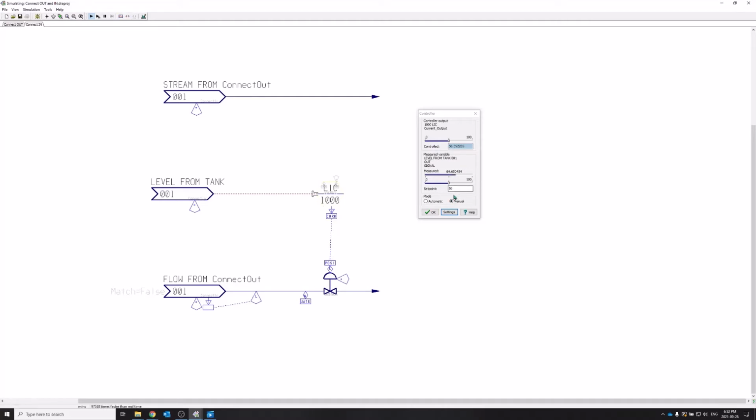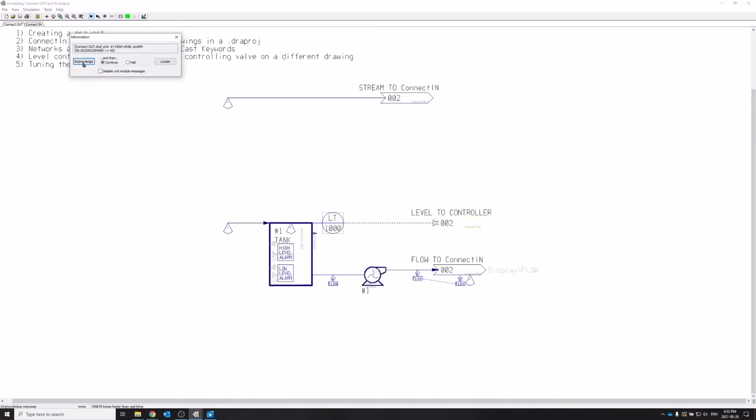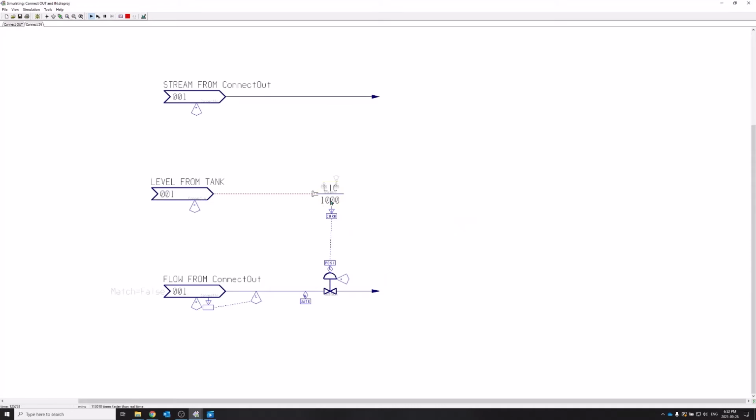So it's overshot a bit here. So that was poor tuning actually. Ugh. I didn't expect this to... oh, you know why? It's because we're still in manual. We never hit automatic. That's the solution right there. Our tuning wasn't so bad after all.